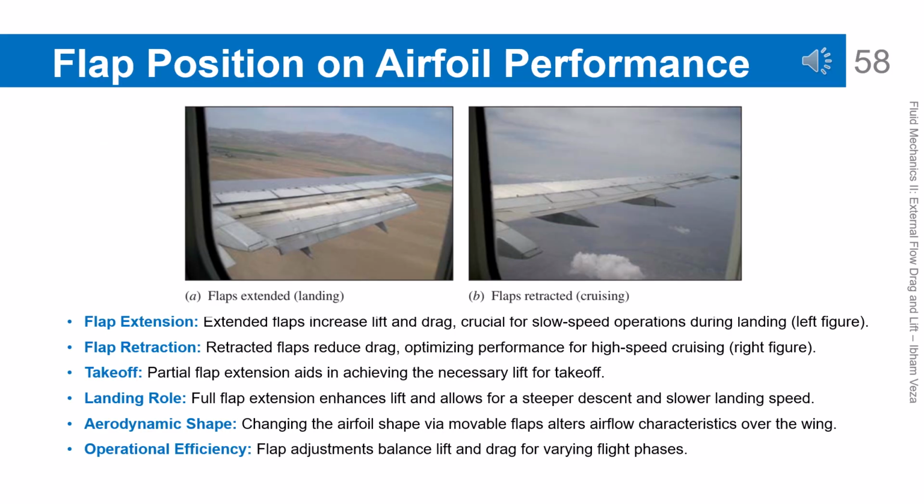Effect of flap position on airfoil performance. When the flap is extended, both lift and drag increase, which is very useful for low-speed operations. When the flap is retracted, drag decreases and the aircraft becomes more efficient for cruising flight.